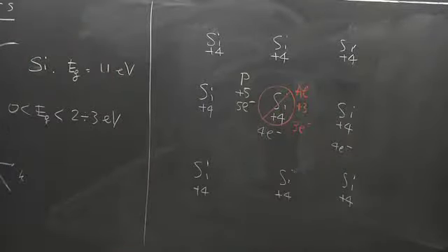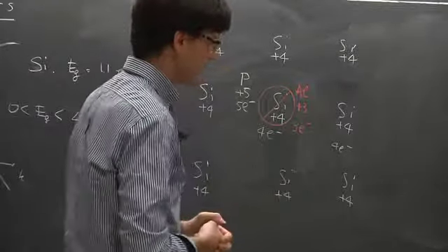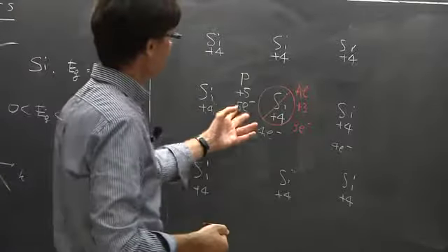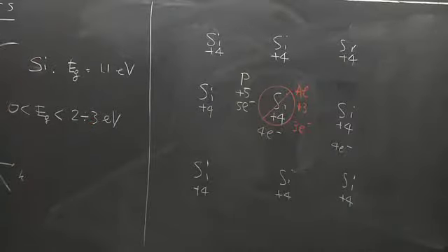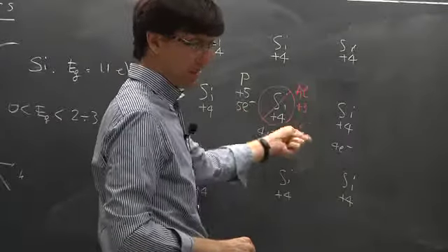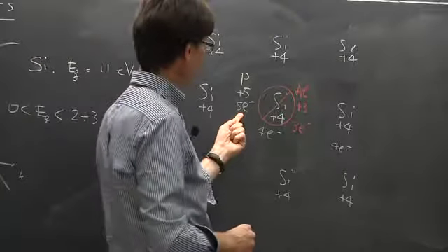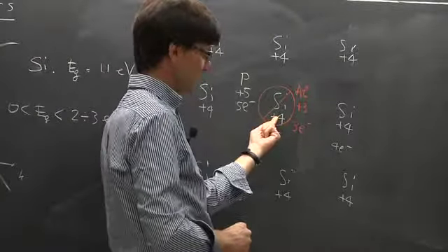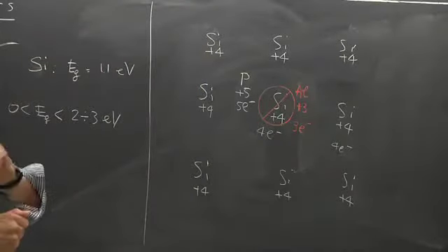And again, I can throw little amounts of phosphorus in the reactor where my silicon crystal grows. And so I can have a small amount of phosphorus substituting silicon while the crystal is growing. And let me actually discuss first the case of phosphorus, and I'll come back to the case of aluminum in a moment. And let me see if I can discuss the problem from a perturbative point of view. So from a perturbative point of view, the replacement of silicon with phosphorus is equivalent to saying that I have an ideal crystal.